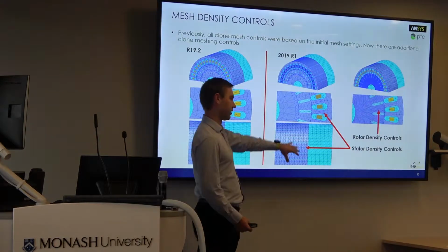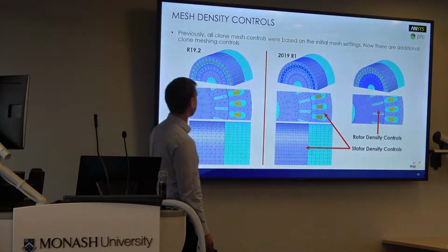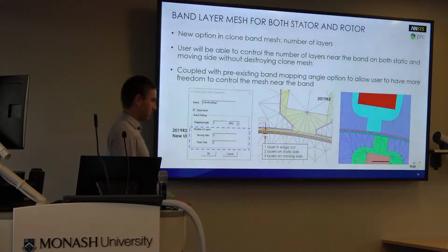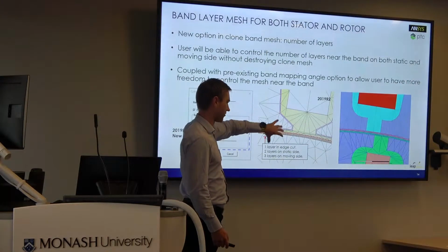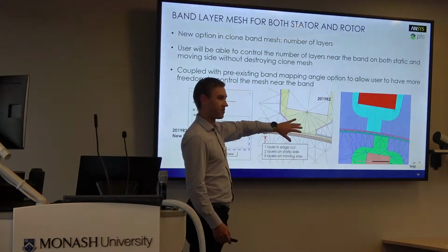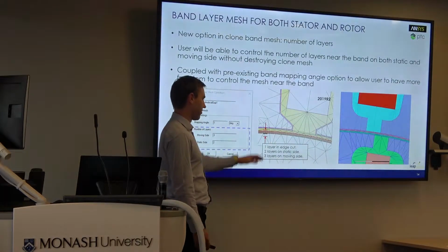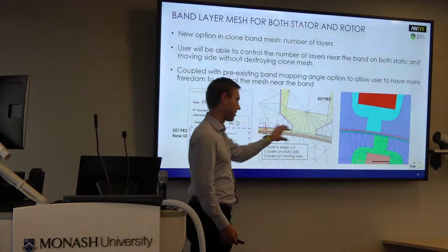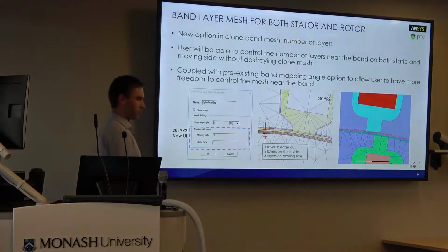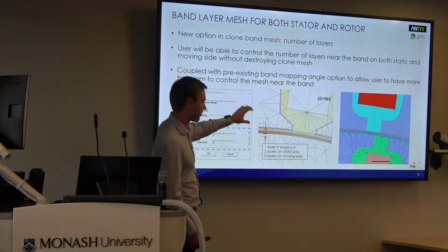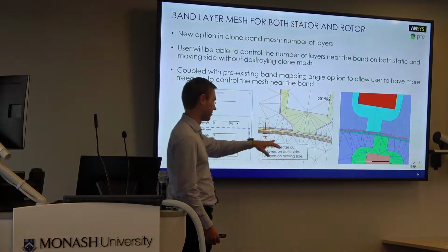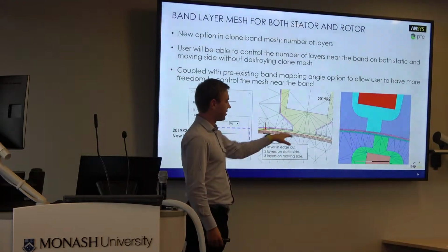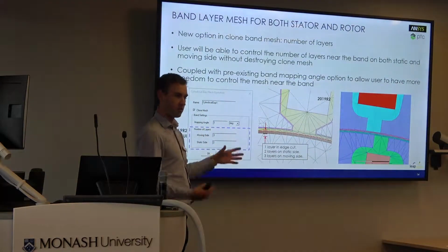This used to be in particular a very frustrating exercise to get it to work. If anyone's been strongly focused on the way that we do magnets and tips of rotors, you'll have come up with your own set of hacks in order to get these really thin layers of elements around the band. We used to do all sorts of things like create custom sheets and mesh them with segments and all that. Now all that's gone. You can leave the edge of the band as a perfect cylinder. You no longer need to segment it.